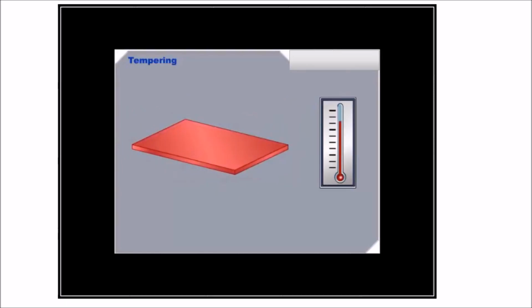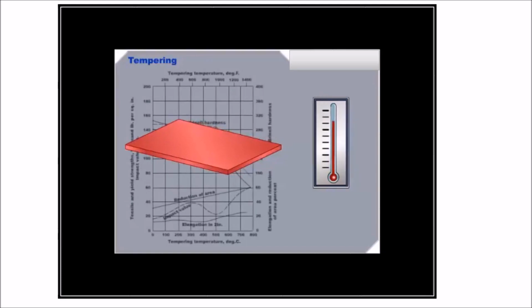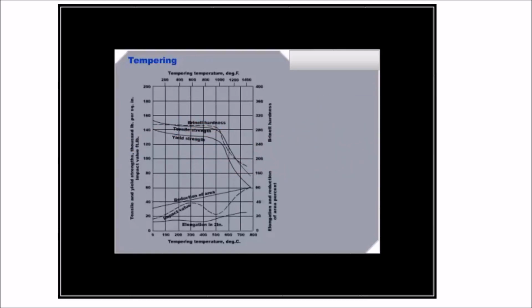Quenching and tempering heat treatment is frequently used to enhance the properties of machinery steels, since it develops high yield and tensile strengths, high yield strength to tensile strength ratios, and improved notch toughness as compared to the rolled, annealed, or normalized properties. An example of the effects of various tempering temperatures for a particular steel alloy is illustrated in the display on your screen.